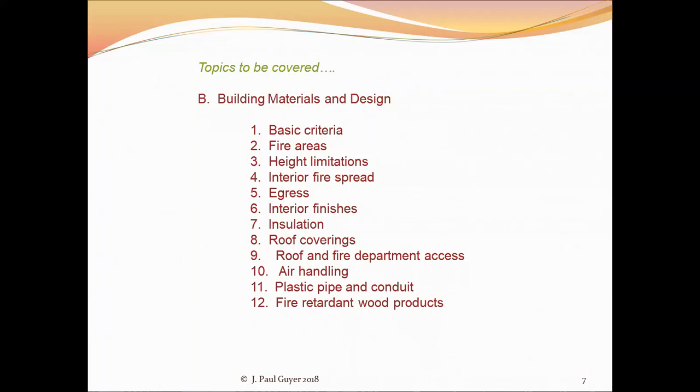Secondly, that you have a control system so that when a fire breaks out somewhere in the building, you automatically shut off the air conditioning system so that it is not forcing smoke around the building.